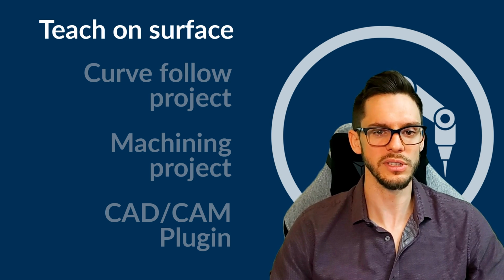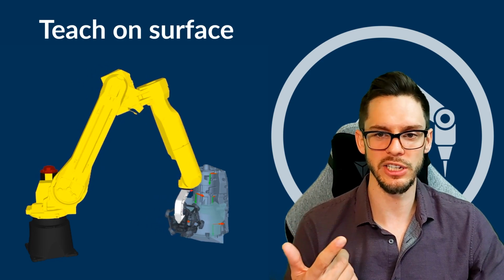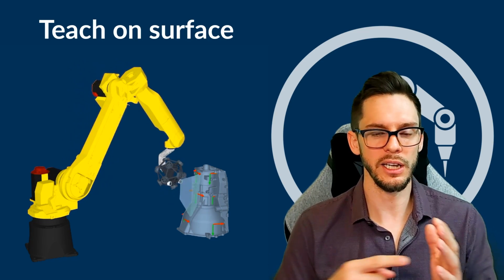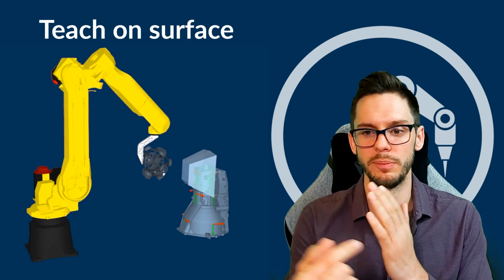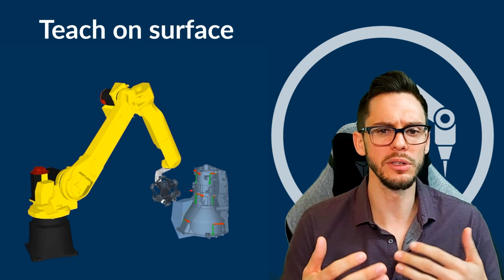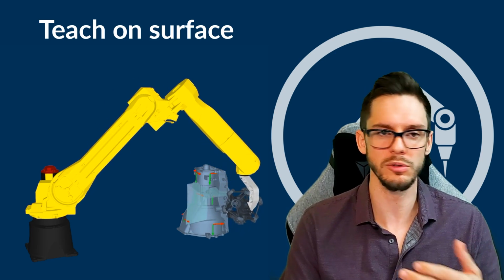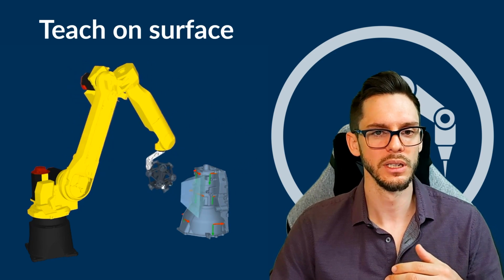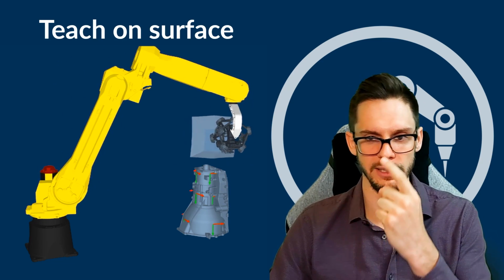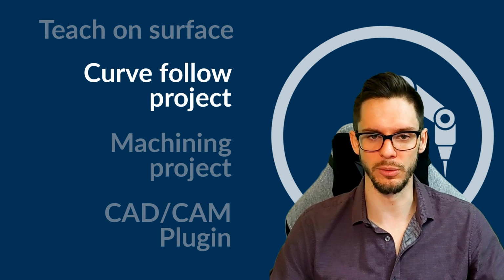So the Teach Target on Surface, or Teach on Surface, is by far the easiest method for RoboDK beginners. You simply import the part either as a STEP file, IGES, STL, or in a few other file formats. Then you activate the feature and you simply click wherever you want on the part to create targets that will touch the surface of the part. I'm not going to give you too much detail right now on this feature because the live demo I will do in a few minutes will pretty much cover it all. The small video you can see right there is pretty much the demo we will do together in a few minutes.